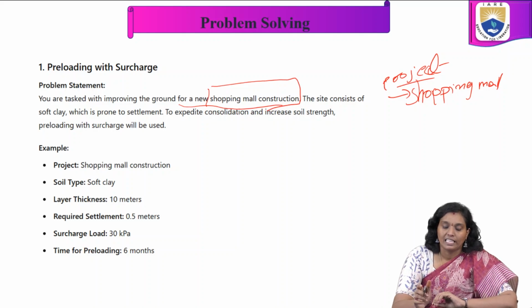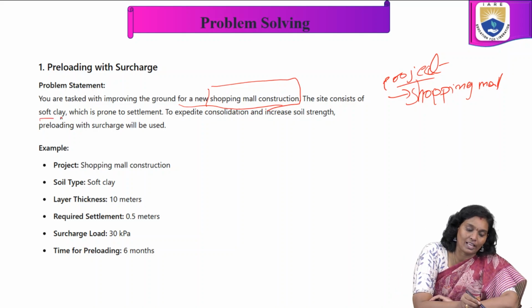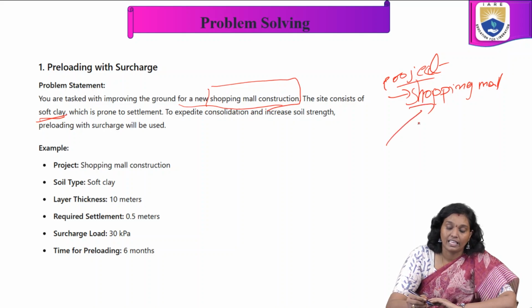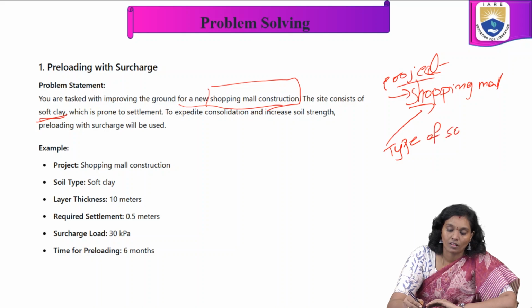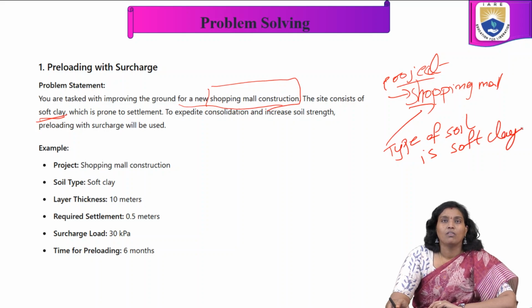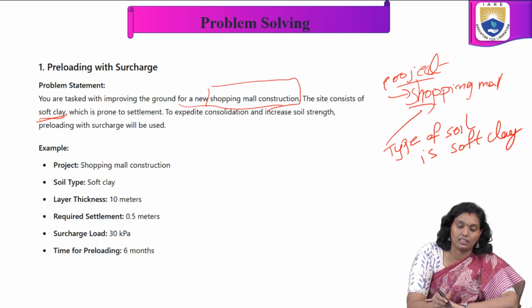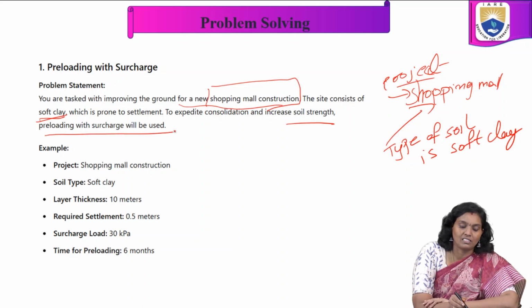The site consists of soft clay. Whenever we are constructing this kind of project on soft clay, there is a chance of settlement. So to exploit this consolidation and increase soil strength, preloading with surcharge will be used.